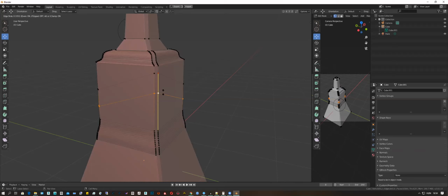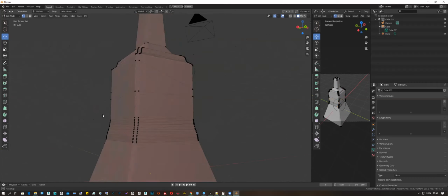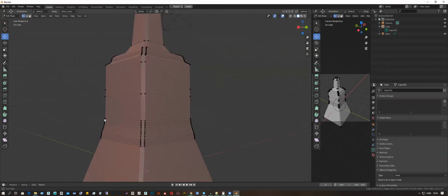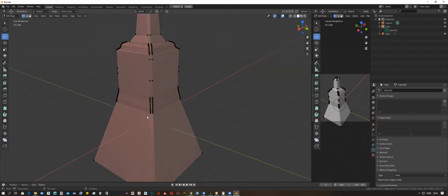I press A, and you see a yellow line appearing, and the red point shows it tries to fit to this end of the edges. If I press F, it changes and it will be using the other side of that. So that's how I can quickly cut straight or to another edge loop. You see? Okay. Any questions so far?